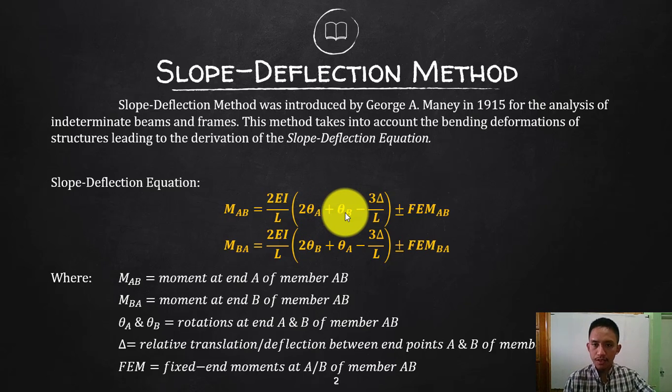Okay, so that is our consistent deformation. We will try to make use of the known deflection or rotations to end up with compatibility equations. However, in this slope deflection, we will be using the unknown deformations. Again, in your CDM, we will be using the known.